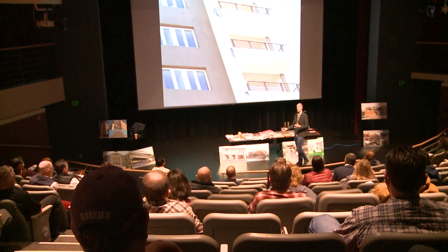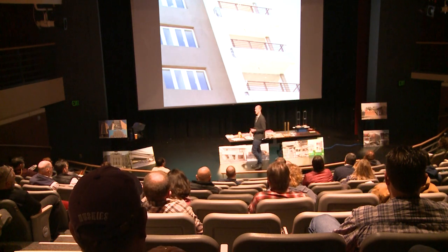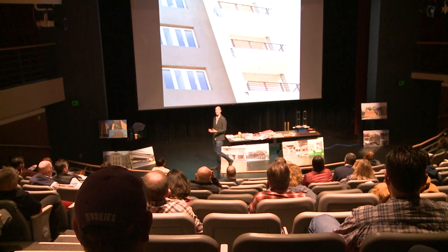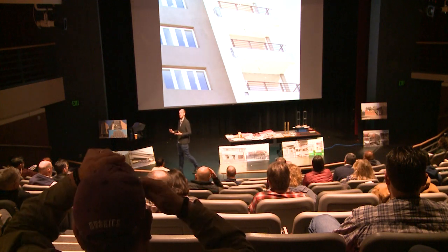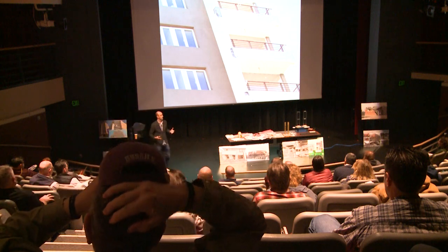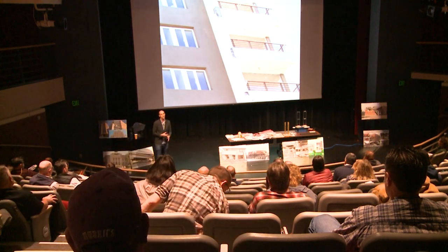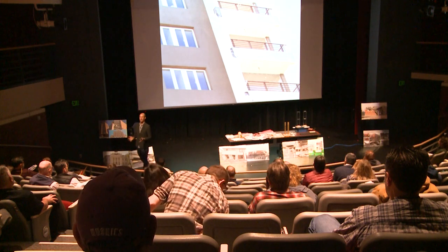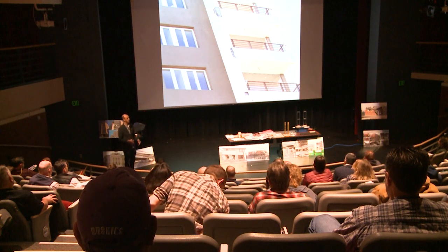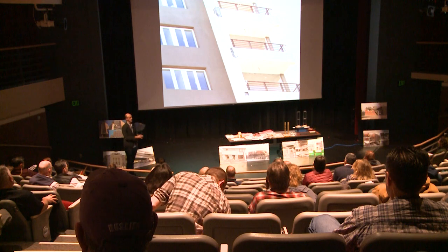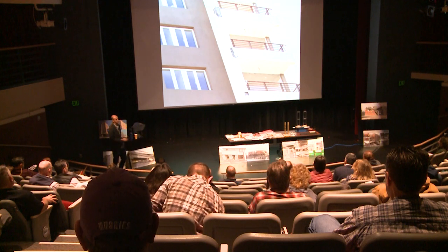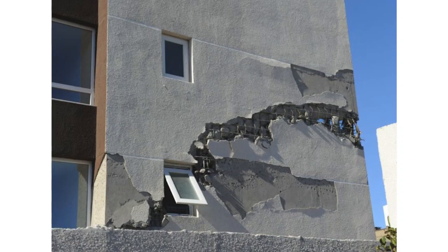And we multiply that by a factor 1.6, then we reduce our capacity. So we inherently build in a lot of factor of safety just by the way that the design codes work and our gravity systems. So if there's some acceleration on top of that, generally speaking, that hasn't been the major contributor to building damage, even though this balcony cantilever may be one brief example of that. A little bit of a tangent, but worth a discussion. So that was the balconies.